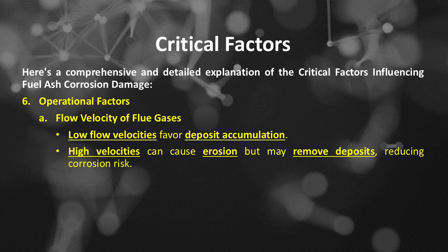Number 6. Operational factors. Number A. Flow velocity of flue gases. Low flow velocities favor deposit accumulation. High velocities can cause erosion but may remove deposits, reducing corrosion risk.